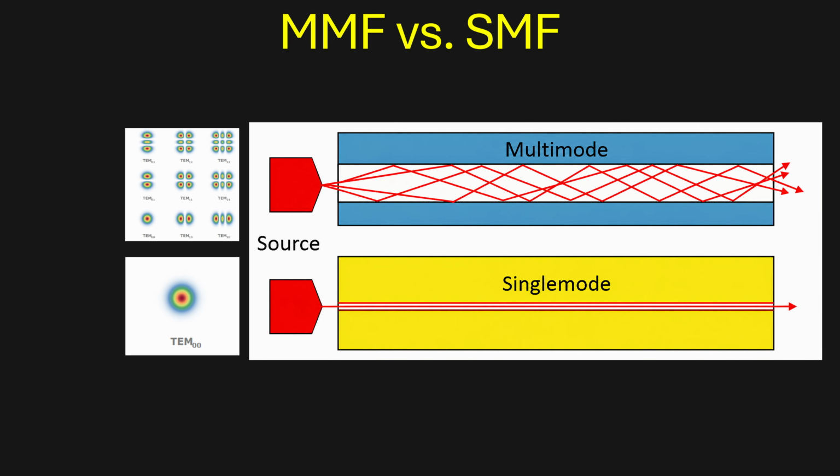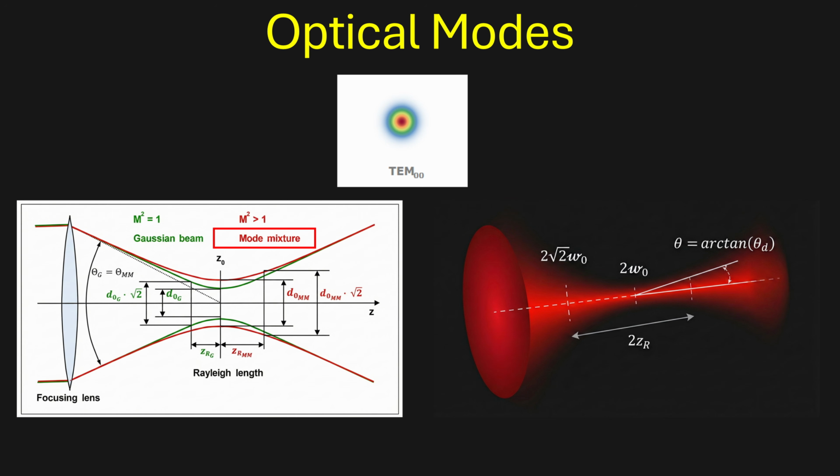For a wider fiber, or for a laser propagating through free space, higher order modes will propagate along with the first mode. Higher order modes result in greater diffraction in free space, and this is why the optics and laser sources in laser terminals and laser weapons measure their beam quality relative to an ideal single-mode Gaussian beam with the m-squared beam quality factor.